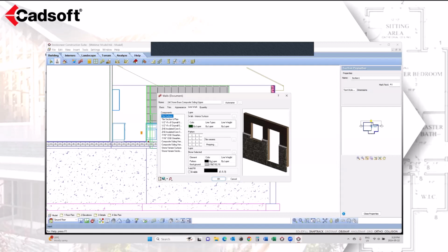So if you really want to illustrate how something's going to look, and maybe the tile itself is teal, or it's fuchsia, or it's gray, or any color, change the background color to give that illustration of what that color is going to be, and then apply your hatch pattern on top of it. And this is for hatch pattern views. So this will go into your working drawings.